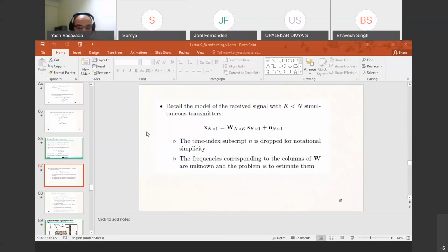Knowing the coefficients of the vectors forming the noise subspace, that equation can be written in closed form. It becomes essentially a polynomial equation, and the frequencies of interest correspond to the zeros of that polynomial equation.